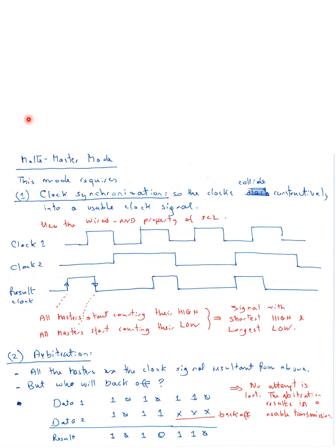The devices themselves don't initiate the communications. So one of the issues that occurs is if there are multiple masters on the same I2C bus. We know that this is a feature. It is allowed to have multiple masters, but let's figure out how this is gonna work in a good way. So in the multi-master mode, the devices are aware there are multiple masters, and they're gonna activate these two schemes that we're gonna see here.